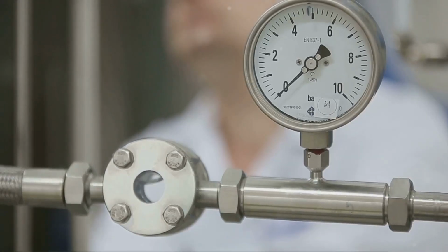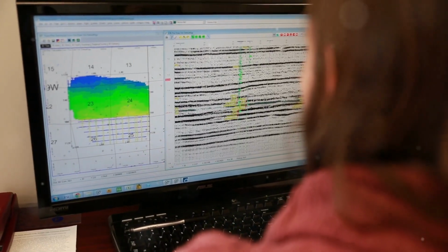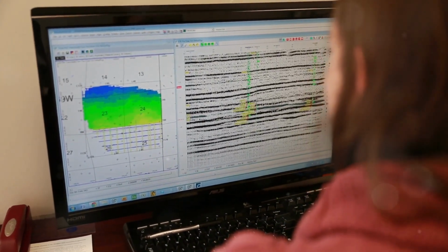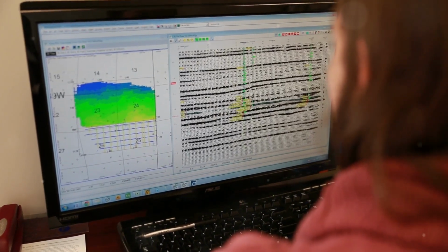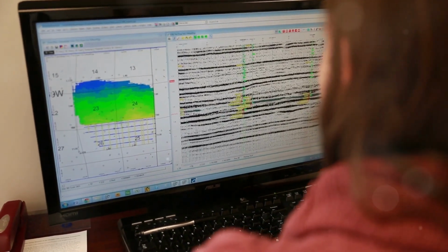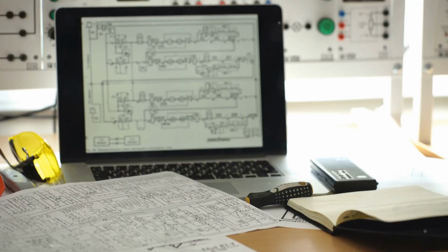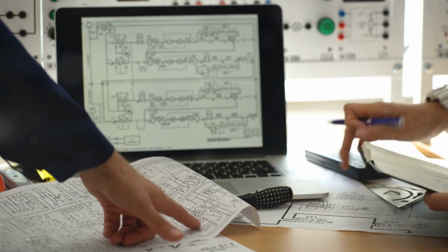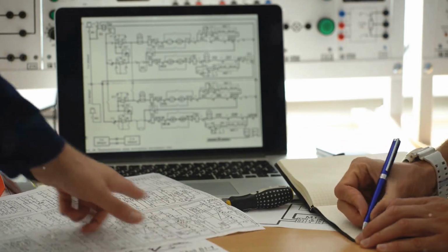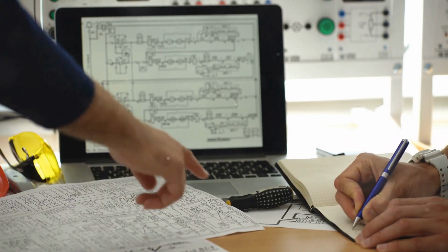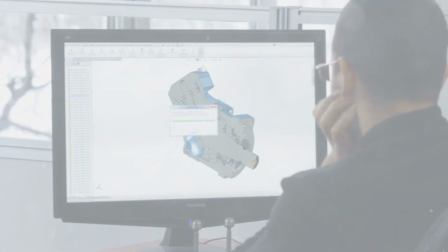Interpreting the results of an FSI simulation requires careful consideration of various parameters such as pressure distribution, velocity profiles, structural deformation, and stress concentration. These parameters provide insights into the complex interplay between the fluid and structure, enabling engineers to make informed design decisions.